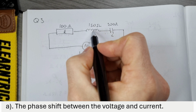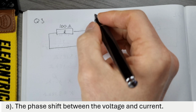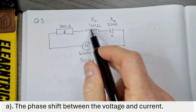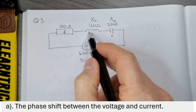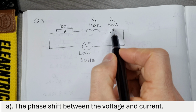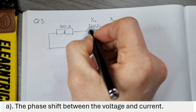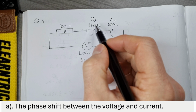Notice in this question that rather than being told the inductance in henries and the capacitance in farads, we're actually given XL and XC straight away. So we don't actually need to calculate these. This is something that can catch students out if they're just used to following the procedure of calculating XL. Students that have learned how to answer the question by rote can get caught out by this sometimes. They'll take whatever information they're given here and insert it into the formula without thinking about it. Don't get caught out by that. If they're telling you the reactance and it's in ohms, then you don't need to work out XL and XC because you've already got it.